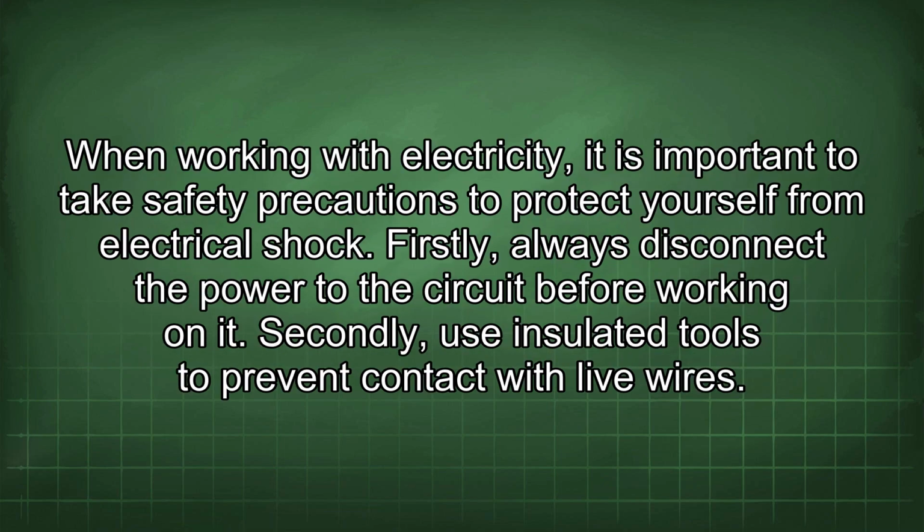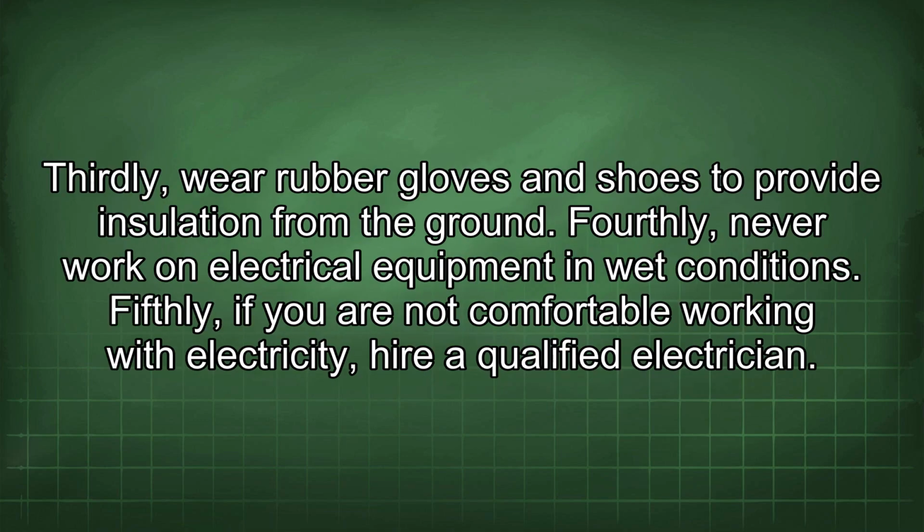When working with electricity, it is important to take safety precautions to protect yourself from electrical shock. Firstly, always disconnect the power to the circuit before working on it. Secondly, use insulated tools to prevent contact with live wires. Thirdly, wear rubber gloves and shoes to provide insulation from the ground. Fourthly, never work on electrical equipment in wet conditions. Fifthly, if you are not comfortable working with electricity, hire a qualified electrician.